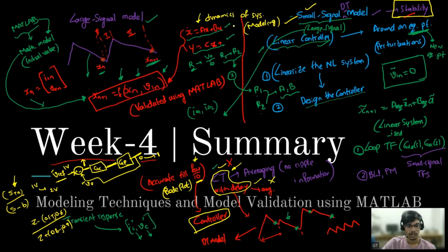Okay, fine. So one last question. This loop transfer function will get the small signal transfer function. That transfer function will give our required bandwidth and required phase margin that we have decided. So if we have set a phase margin of 60 degrees from the small signal analysis, the transfer function will give a phase margin of 60 degrees, right? So that controller will deliver.